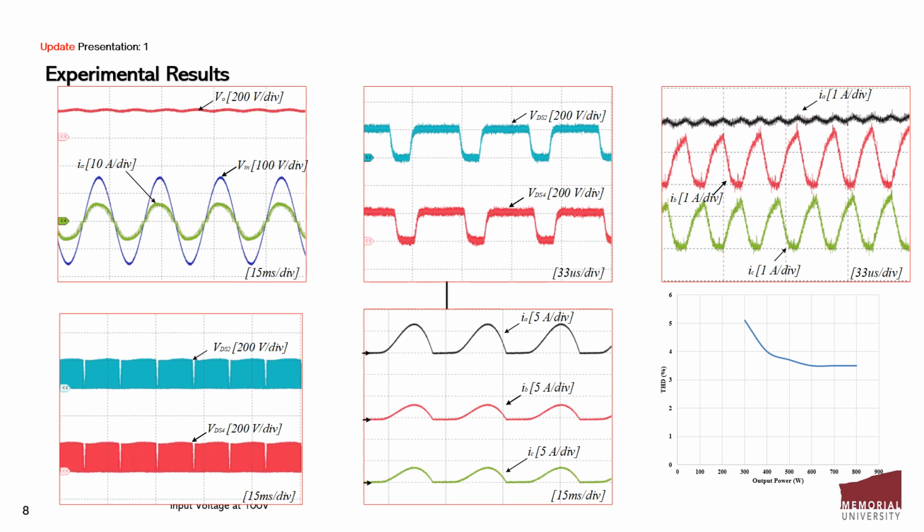The zoom out inductor current is the one on top right. Because the inductor is a coupled inductor, we can see it doesn't discharge directly straight to the bottom, but there is a slow discharging and then slow charging at the very top. The effect of the coupled inductor is the reduction in the current ripple.